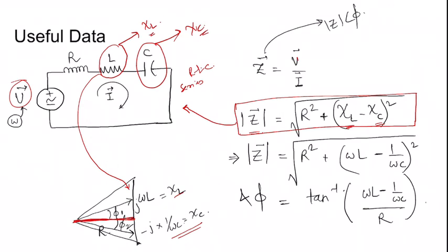x-axis. So now along the real axis, R is like this, and the net reactance offered by combined effect of inductor and capacitor, if it is in the plus direction, when XL is greater than XC, then phi 1 will be like this, net effect in the anticlockwise direction. If not so, then XC is greater than XL, then the net effect will be in downwards direction, so phi 2 will be in this direction, minus.